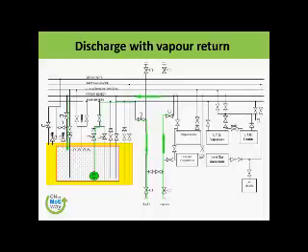You are filling the shore tanks, and from the shore tanks you are taking their vapor. So it is a win-win situation for both of us. They do not have to reliquefy vapor to put in their tanks, and we do not need to use the vaporizer to put vapor in our tanks.